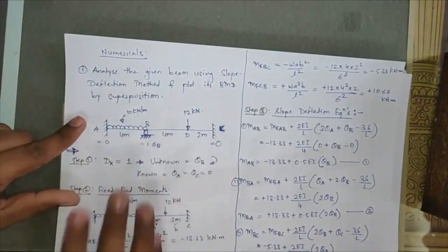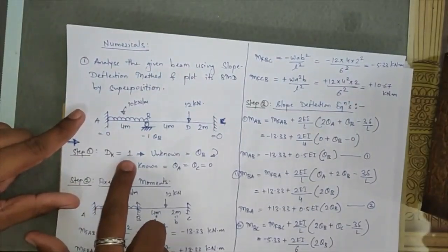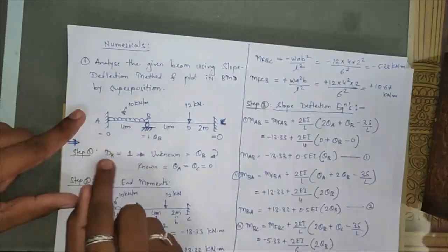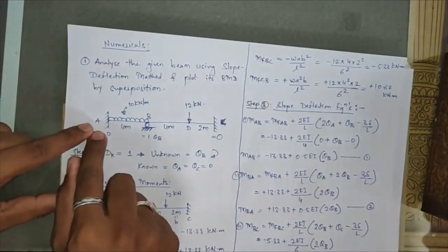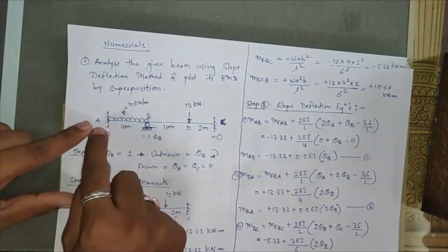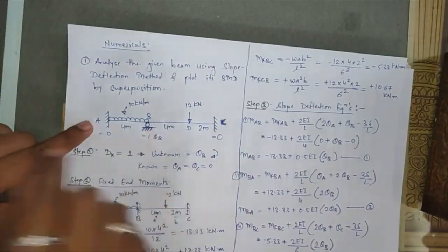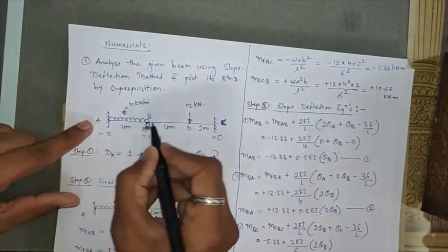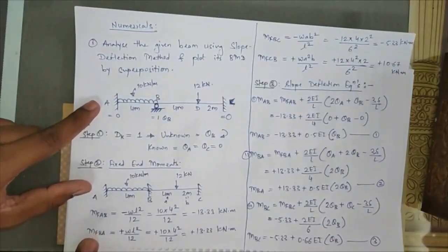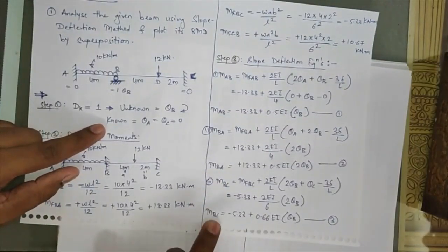So what are the equilibrium conditions? These conditions will be in number equal to your degree of freedom value. If your value comes equal to 1, you will have one condition. If your value comes 2, you will have two conditions of equilibrium. So at joint A, can I say your moment will be 0? No, you cannot say. So the condition of equilibrium cannot occur at point A. Same way it cannot occur at point C. So which joint is remaining? Joint B. Now to keep this joint in equilibrium, what two moments are occurring, that we have seen. First is your MBA moment occurring here, and the second moment occurring at joint B is MBC.